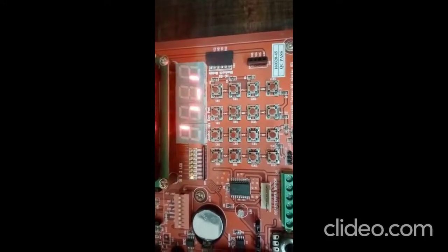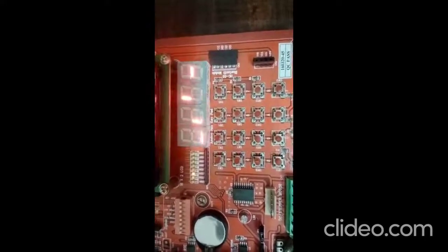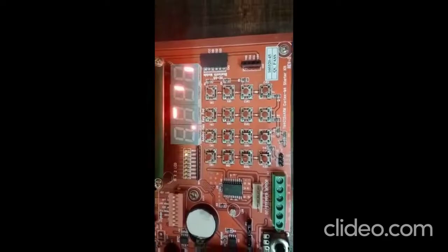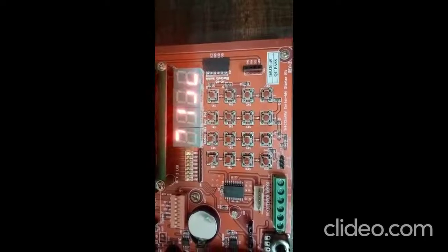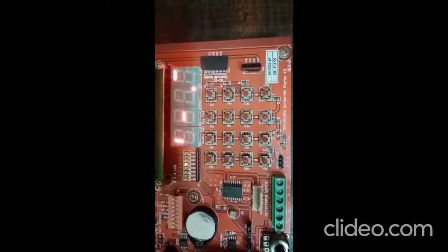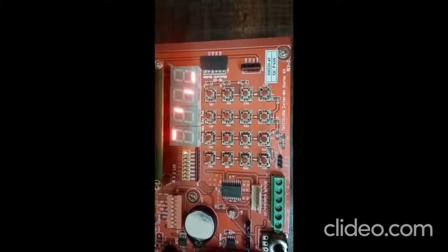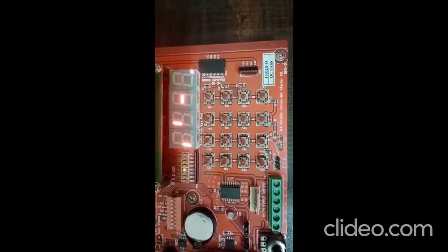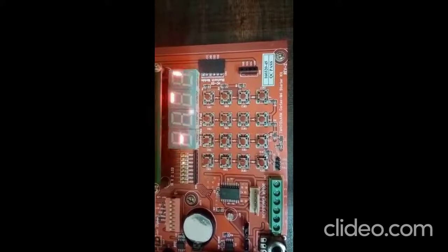Here we developed the program for the LEDs only, but that LED stick is also connected to the 7 segment display, which is also running. That's why we use pin PE4. Actually, pins PE2 and PE3 are used for flashing the LEDs, and pin PE4 is used for the 7 segment display on that stick, right? Thank you.